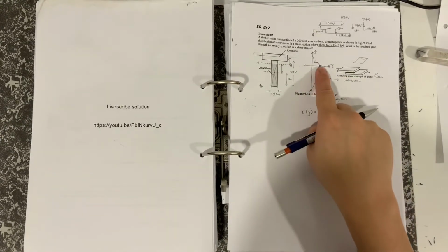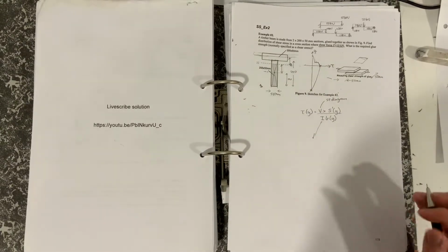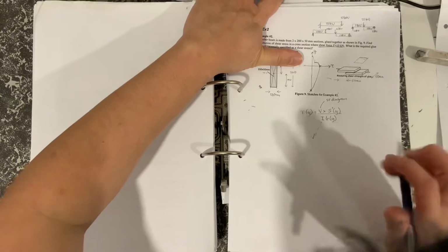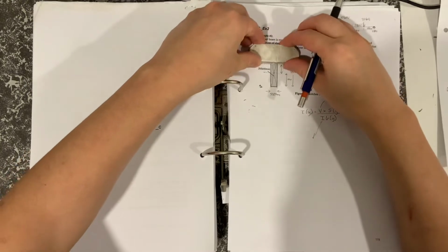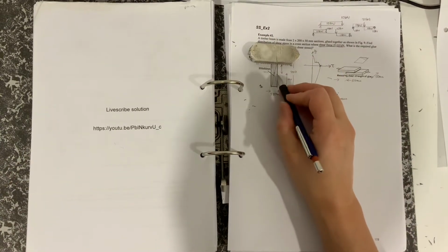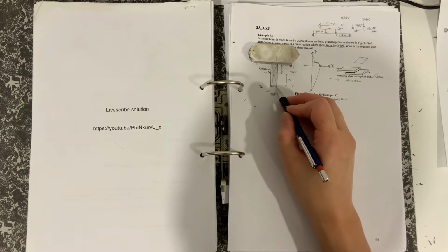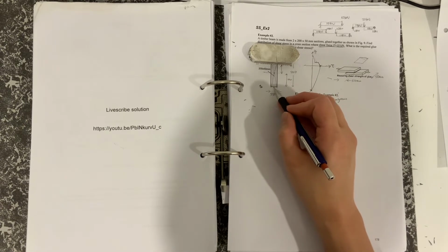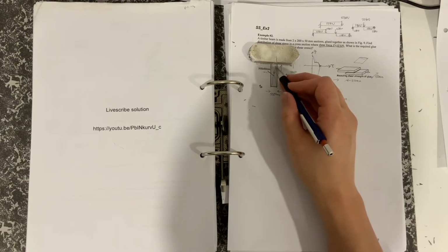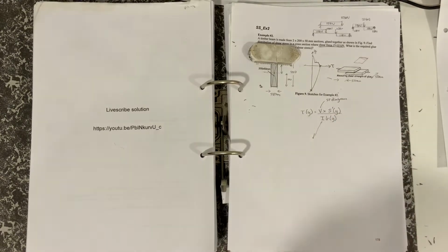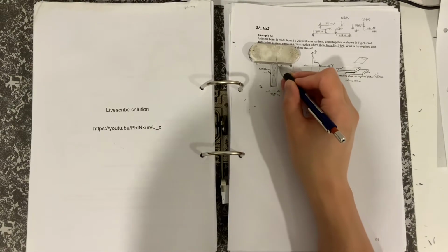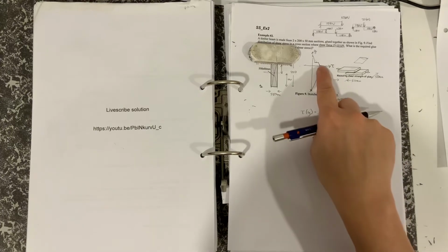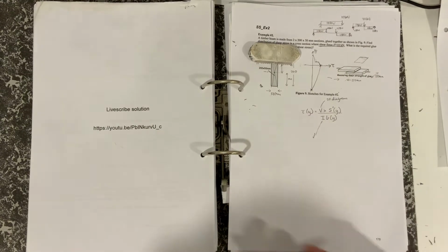If you wanted to work it out at the neutral axis, then what we would do is cover that bit there, and take just that portion there. So that's quite handy, so let's just get rid of that. So we would concentrate on this section here, work out its dimensions, work out halfway down so that we can work out the S-Y, and we would then work out the area of that section there, and that would give you that value of shear stress at that position.